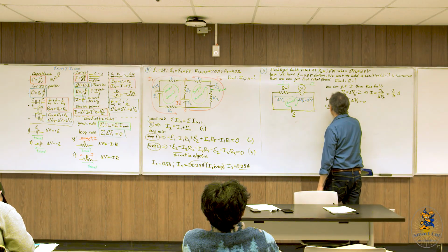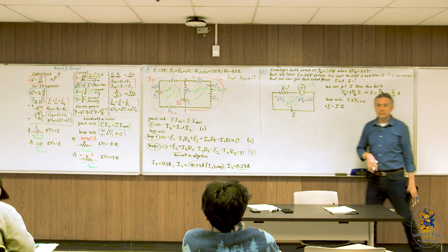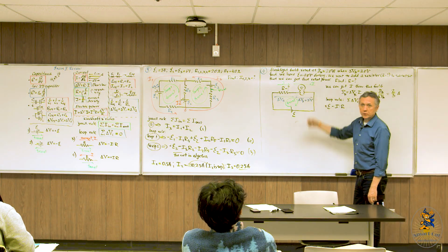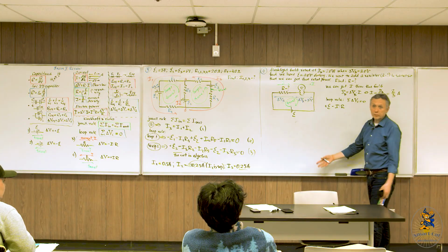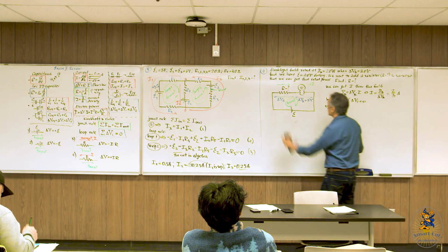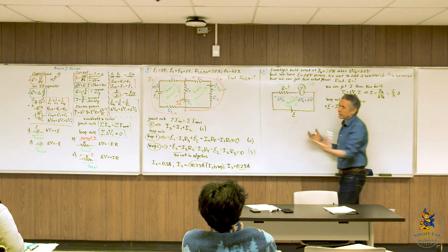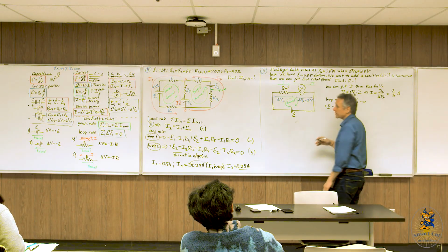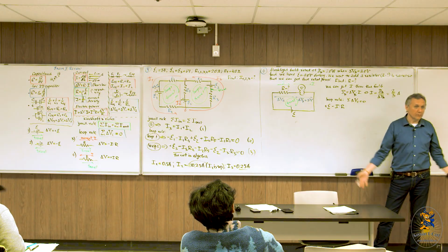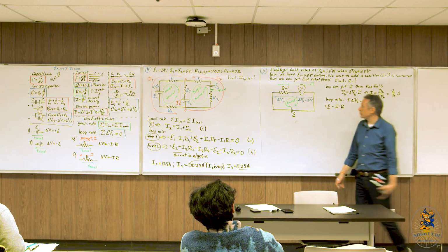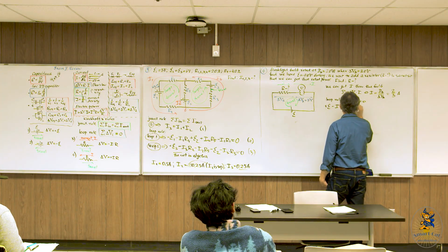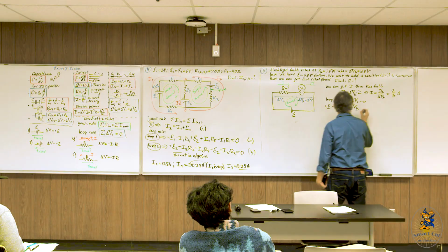All right, so it will be minus I times R, with R not known. And there will be, of course, voltage drop of 3 volts, and again, it will be minus. So again, travel direction this way, current that way. So through the resistor, of course, it will be negative contribution. But in this case, it's not just IR, we know the potential voltage drop which we want to get. So it will be minus delta V_B. Minus delta V_B. And we're back to the starting point, so it's 0.